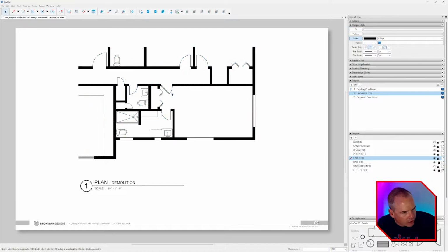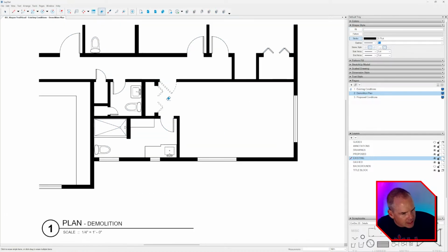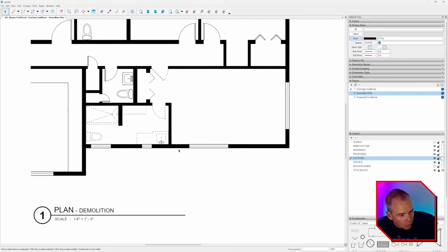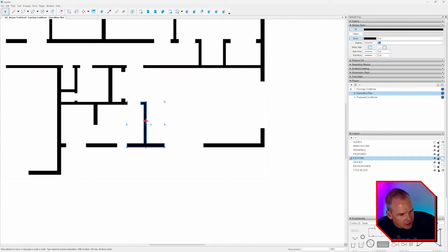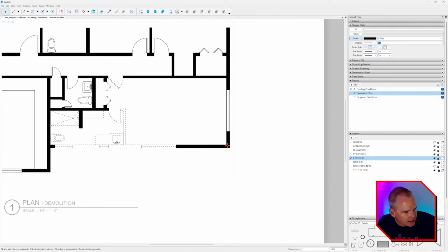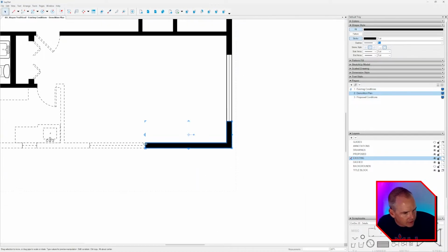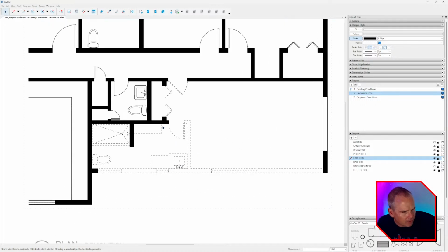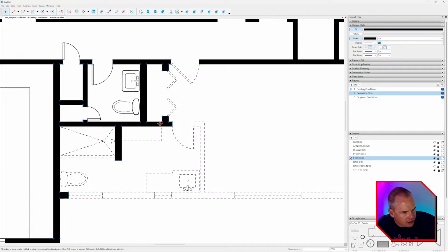And then I'm going to recreate our demolition plan by trashing these things, and see as I delete or demolish a wall or demolish a window, we can see those things go away. So I can delete that, and as I'm trashing this stuff, it leaves behind the dashed lines. So then I can select that, scoot it over there. We're going to trash all of this.